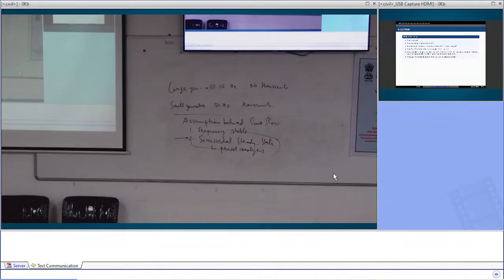The assumption that I can do load flow, and in power systems when you are simulating synchronous generators or power system, whatever you are simulating, every integration instant you do a load flow. That means that every 10 milliseconds or 5 milliseconds or 2 milliseconds you assume that the entire network has come to steady state. I mean, if it was just an assumption, it was just done for convenience, then we would not be able to predict things so accurately.